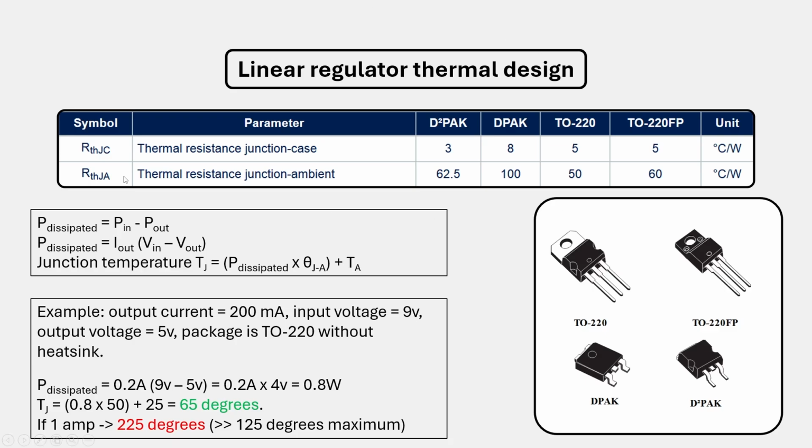But get it through your head that if you really need a heatsink, then you probably shouldn't be using a linear regulator anyway, or maybe you're using the wrong package, wrong design, and so on. I'm talking about normal low power devices, but not those very, very high power devices that can require a heatsink by definition.